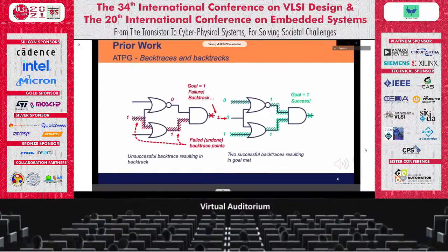To avoid this upper limit, most ATPG algorithms employ backtracing subroutines. These subroutines trace backwards through a circuit starting from an objective, such as exciting or propagating a fault, and attempt to find input assignments which accomplish the objective. Multiple backtraces from an objective may be required to meet the objective. But if these input assignments accomplish the final goal, that is, find a test for the fault, then at most I input vectors must be simulated, which is nothing compared to the theoretical maximum of 2 to the power I.